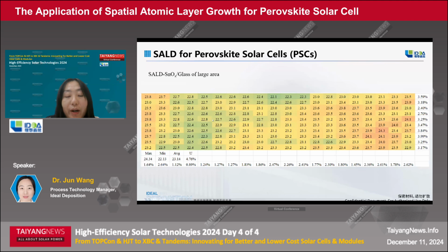For this one, the coating area is about 2 meters by 1 meter on glass. Film thickness at 200 positions was measured, and we can see the lateral non-uniformity and the perpendicular non-uniformity are around 4% and 3% respectively. The overall thickness non-uniformity is about 4%.